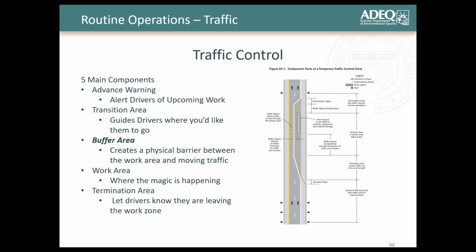Your third main component is the buffer area. This is the controversial area that's not always included in text, right? But every great traffic control training has this buffer area, which is just an empty area that creates a physical barrier between the work area and the moving traffic.